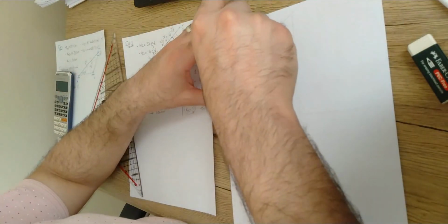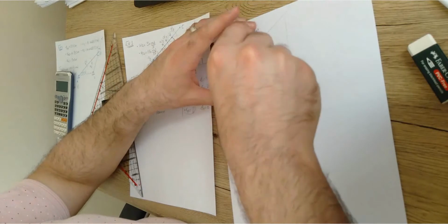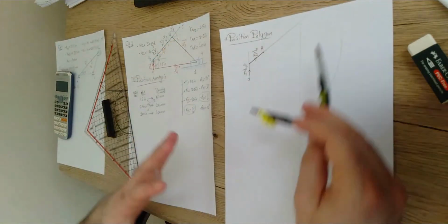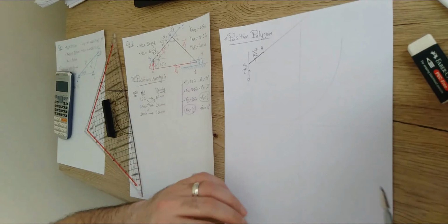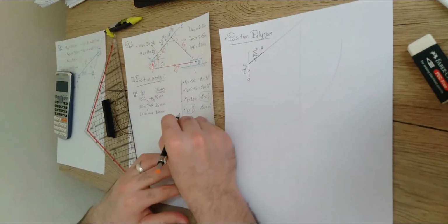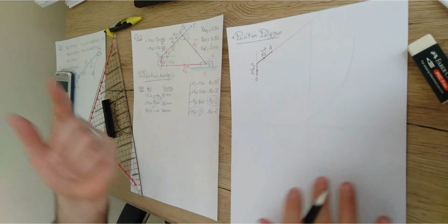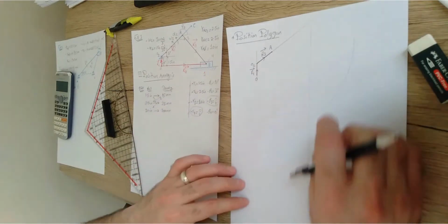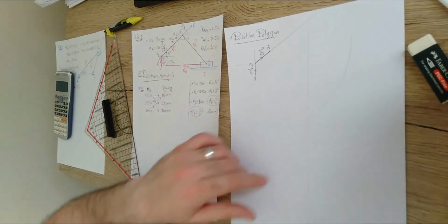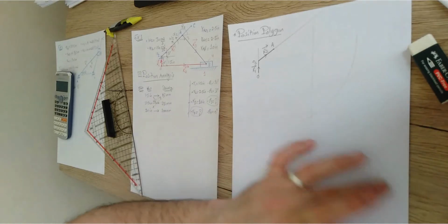And draw a curve as we agreed in this way. So this curve should be the locus for point B. It means that point B should be located somewhere over this curve. Then that's it. We said that for a vector with a known direction, we can only do one thing, which is just drawing a curve. For the other vector with a missing magnitude, we can do 2 steps of the 3 steps.